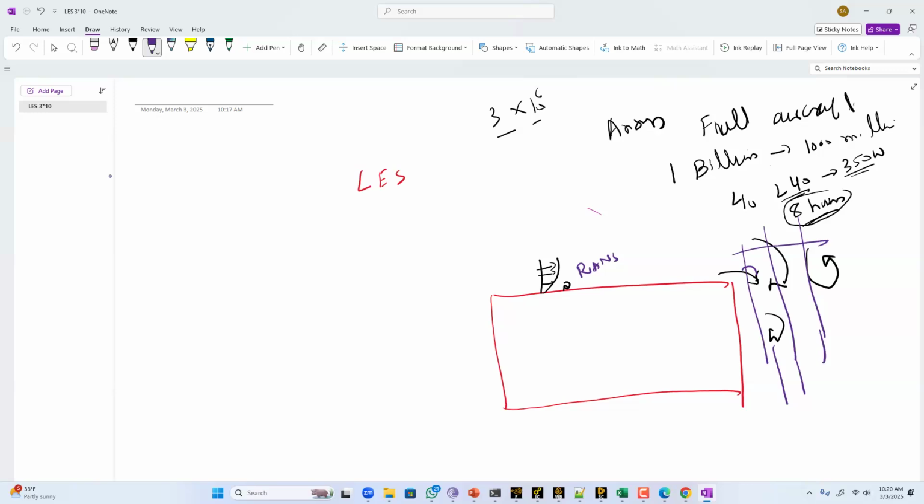We have to make the element size compatible with this value, like k power 3 by 2 divided by epsilon, and then you have to divide this size by 6 again. So first you have to get the size of this eddy from your full RANS simulation, and then you convert the mesh based on those results by dividing the mesh size by 6, and you will get the mesh for the DNS and the LES. But for LES in this region, because the length scale will be very small, the boundary mesh will require a lot of cells. So the recommendation is that you should go with DES.